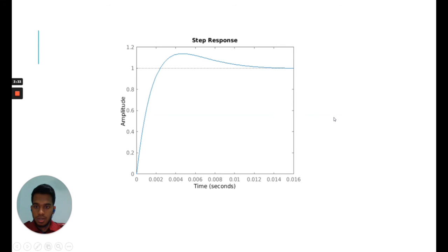So here we have KP 20 and KD 20. The graph shown here has an overshoot. This graph shows that there is an overshoot and that the settling time increases. As a result, this system is unstable. To reduce the overshoot, we increase the KD.